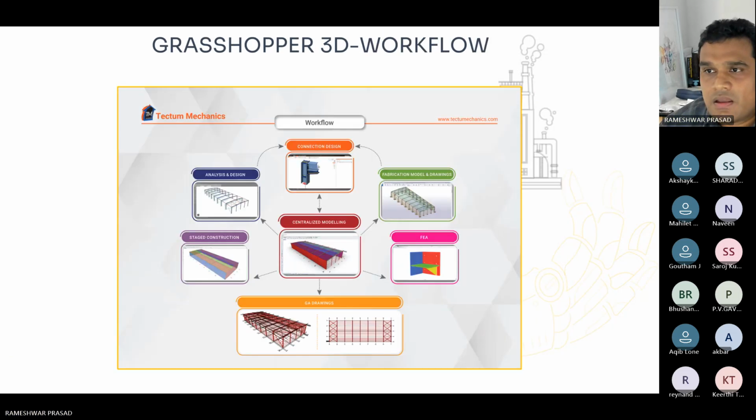Okay. So what is the workflow? We model a structure in Rhino using Grasshopper. You can actually model it manually as well. One of the demonstrations will actually show how you can manually model in Rhino, almost similar to STAAD.Pro, and then import the elements into Grasshopper and use the same workflow of exporting to SAP2000 or Tekla. So you model your structure in Rhino using Grasshopper, and then you export it to Tekla.